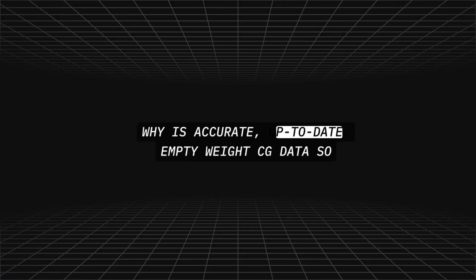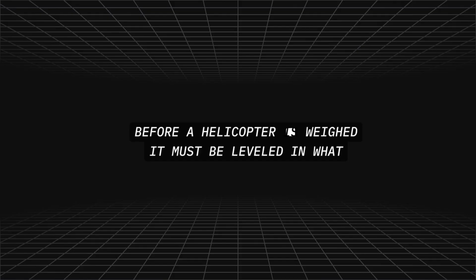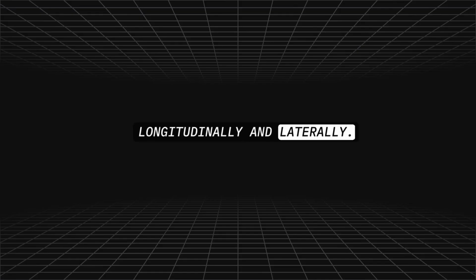Why is accurate, up-to-date empty weight CG data so important? All other weight and balance calculations are based on empty weight CG. Before a helicopter is weighed, it must be leveled in what directions? Longitudinally and laterally.